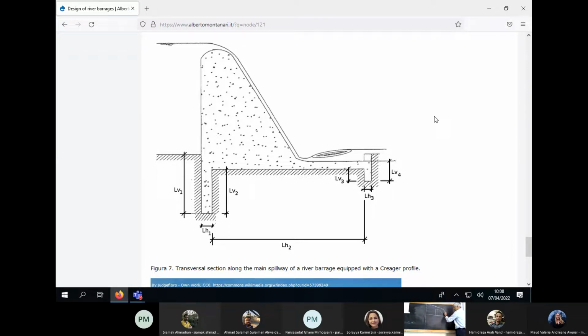Why may it be problematic? Because then here you have turbulence and then you have downstream the water level, because there is the risk that a void is created here, because the flow basically has some cohesion with the air and brings the air out, and therefore here, as I said, the void may be created, which means that for the atmospheric pressure over the flow, you may have suddenly the flow collapsing against the structure.